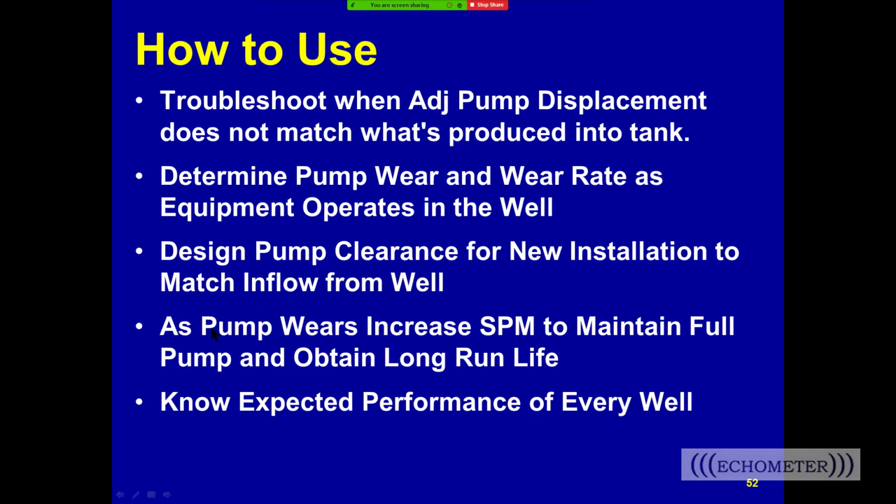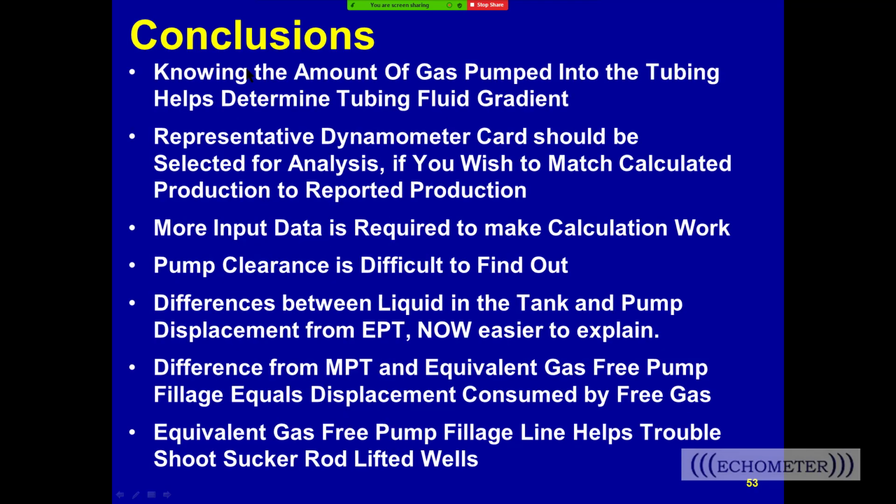That can help you. And as the pump wears, in some cases, you can increase your pumping speed and maintain a full pump and increase your run life. So some operators have done this successfully, where they run a fairly tight clearance at a slow speed to have high slippage, and as a pump wears, they increase their pumping speed and maintain a full pump as their pump wears. But by using these calculations, you should be able to know what your expected performance of every well that you have is.